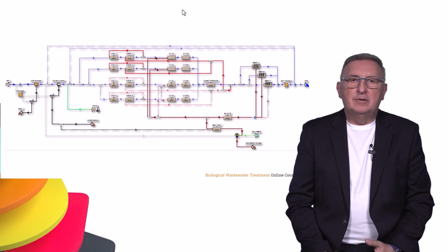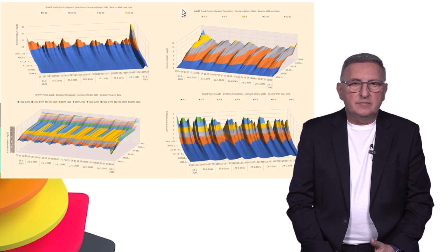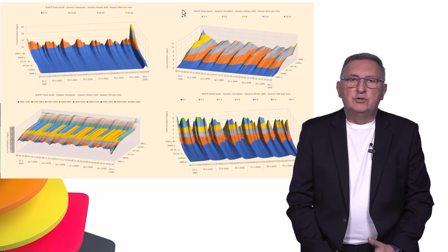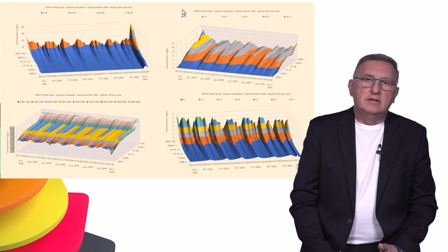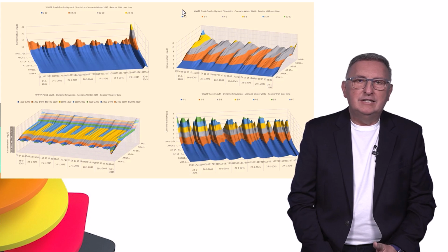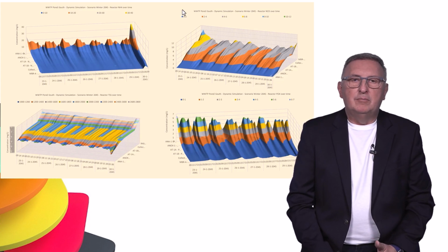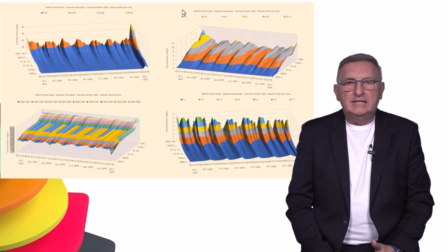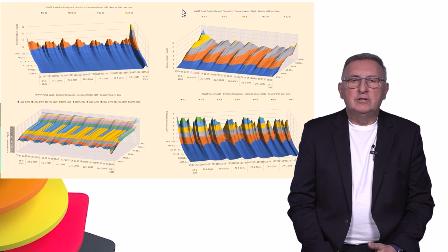We applied, as I said, the BioWin model and BioWin simulator, and this is an example of one of the 4 wastewater treatment plants, and as I said, the other schemes are very similar to this one. And then, based on the modeling exercise, using our static model and then a model which is calibrated on sampling campaigns results from winter and summer 2019, we got to this stage where we could model the situation in 2045.